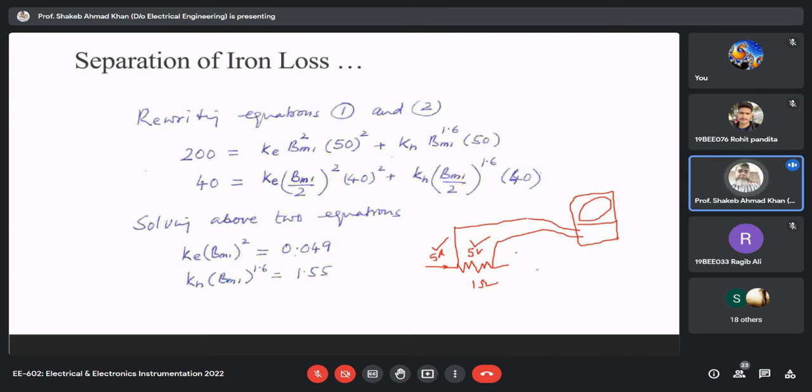Although there are dedicated methods and circuits used for measurement, operational amplifier based circuits, you can convert the current signal into the voltage signal. But this is the simplest way, although not a very good way, because whenever you pass a current through a resistance, losses take place, so you lose energy. If you don't want that, then operational amplifier based circuits are there.